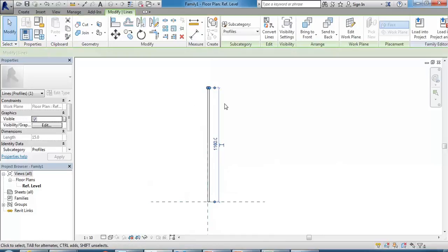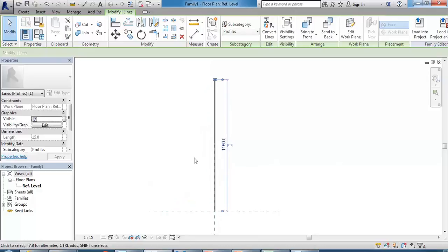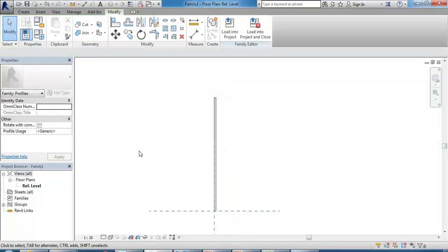And then the top there is going to be the height of my handrail, or the balustrade. So I just want this to be a solid sheet of glass. And so I'm going to make that 1,000, standard railing height. Done. That's it. That's my profile family.